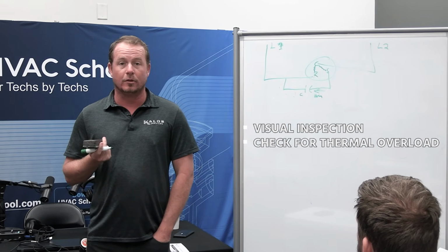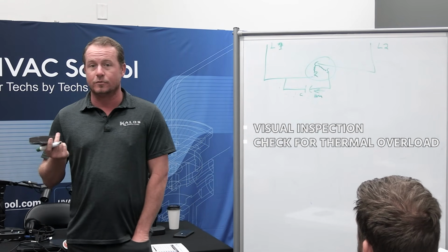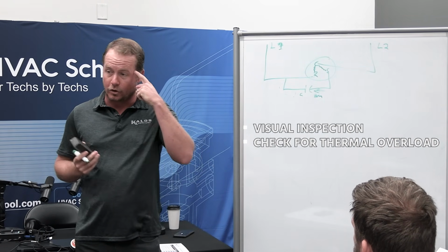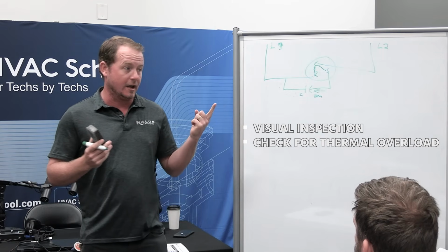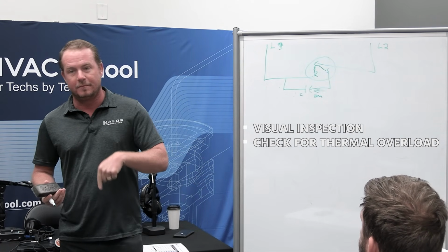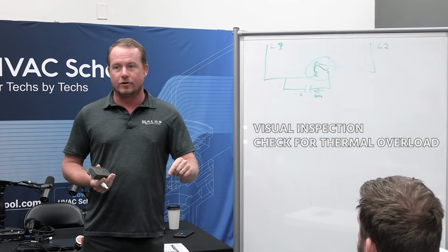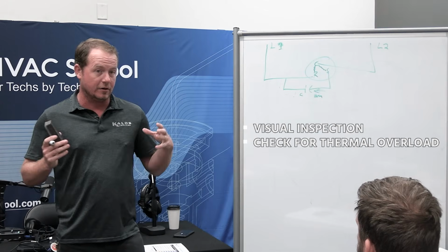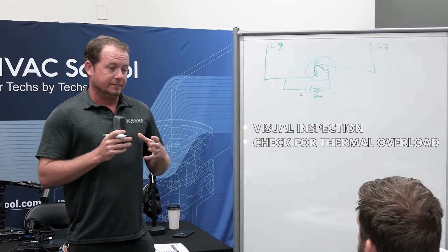Well, if it's in thermal overload, it is in thermal overload, because when it tries to start, it shuts off and goes into thermal overload. But if you heard it trying to start, thermal overload is not the problem. It is locked and overheated. Thermal overload is a result of it trying to start and being locked. What do we do next?